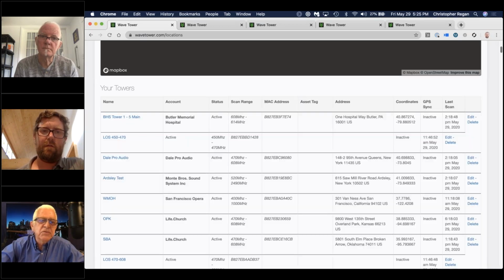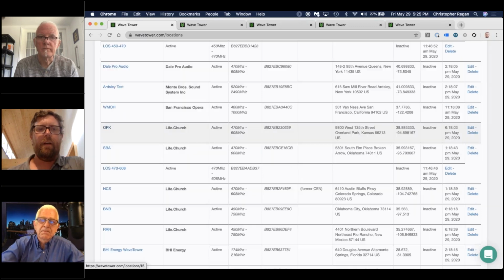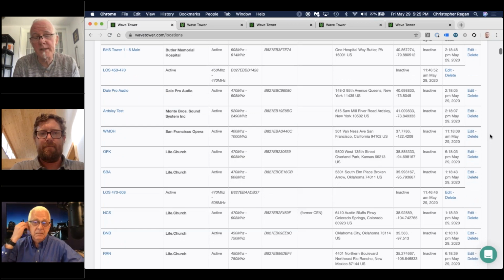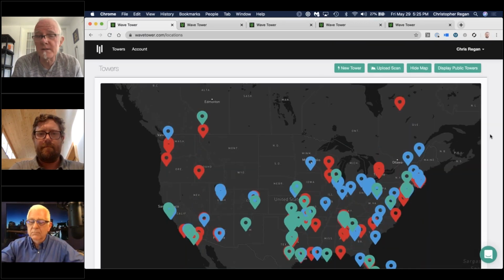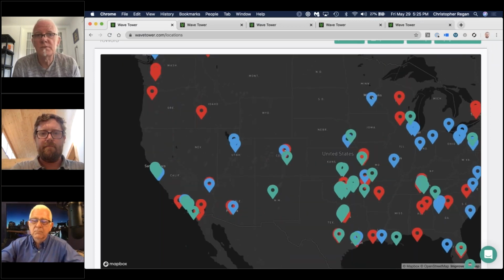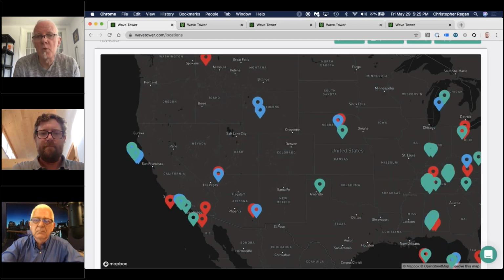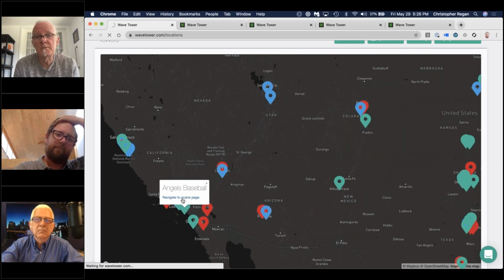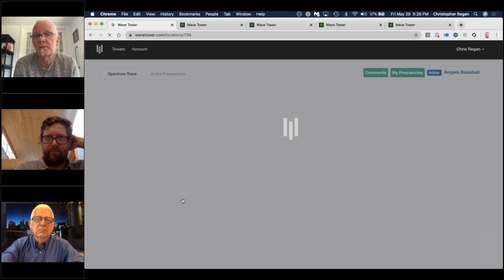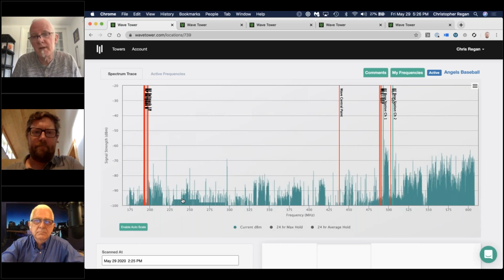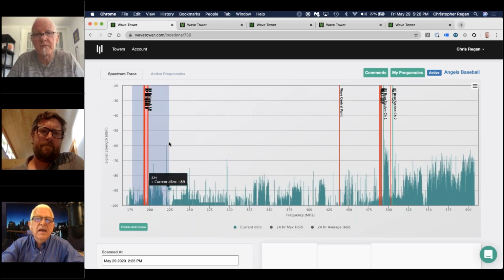you use the same antenna? Well, you'd be better off using a more specialized antenna for a range. The antenna that comes with it is for UHF wireless mics, so it's good for that. If you want to monitor VHF or something else, having a more suitable antenna gives a better result. Nobody's got an antenna that goes from DC to light, so you'll still get something, but an antenna that's more appropriate will give you better information.